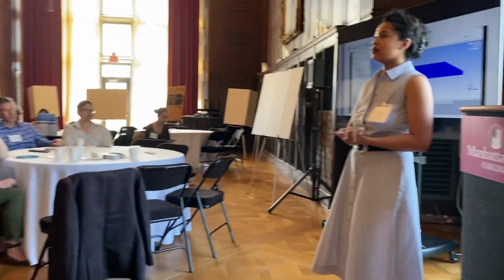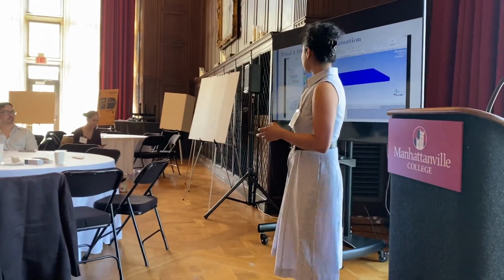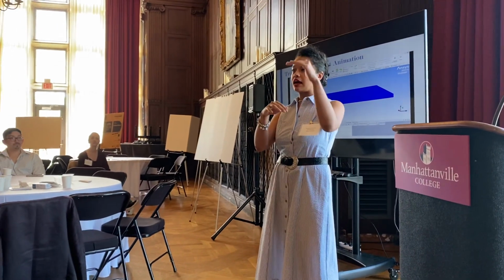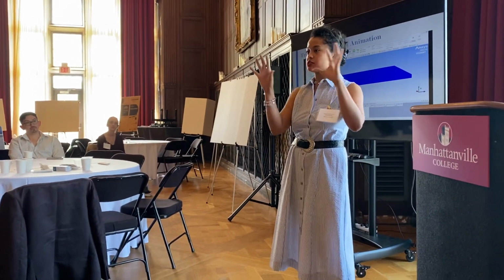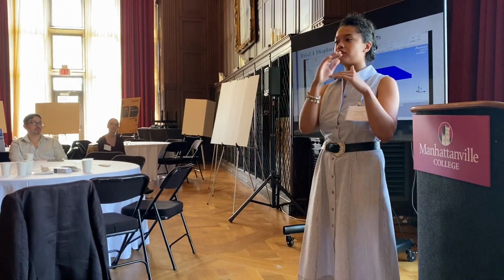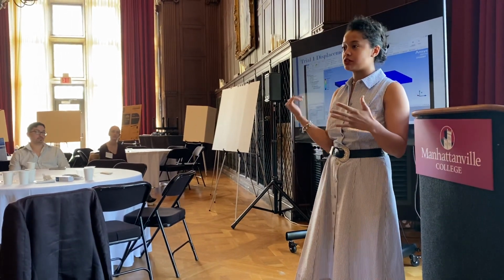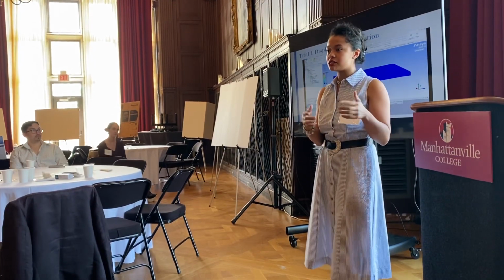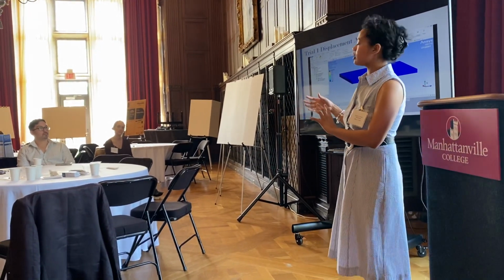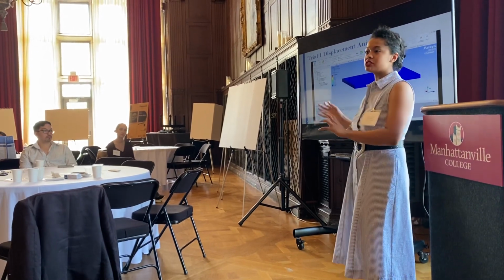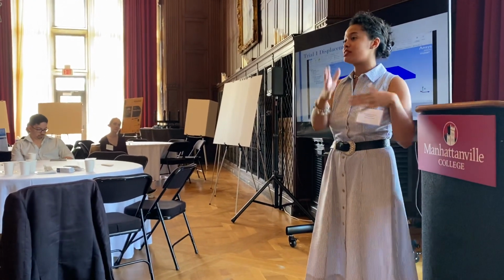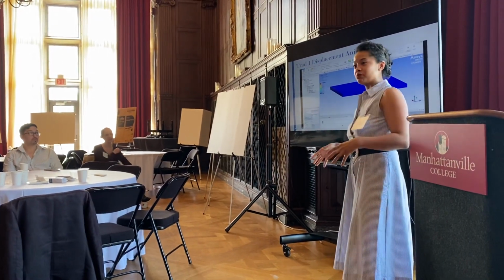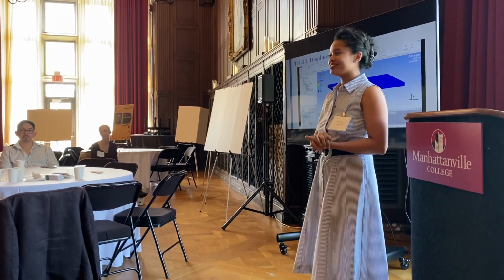How would that look? So when I'm inputting the forces into the software, it breaks it down into the X direction, Y direction, and Z direction, since we're dealing with 3 dimensions. We only did a force in the Y direction, -50 newtons. So in order to make it more realistic, we would add it in other directions. And there is a current body of work about clothing simulations. However, it's mostly for animation. So we would take some from that body of work and do it more from a mechanical engineering perspective. Awesome. Cool. Thank you.